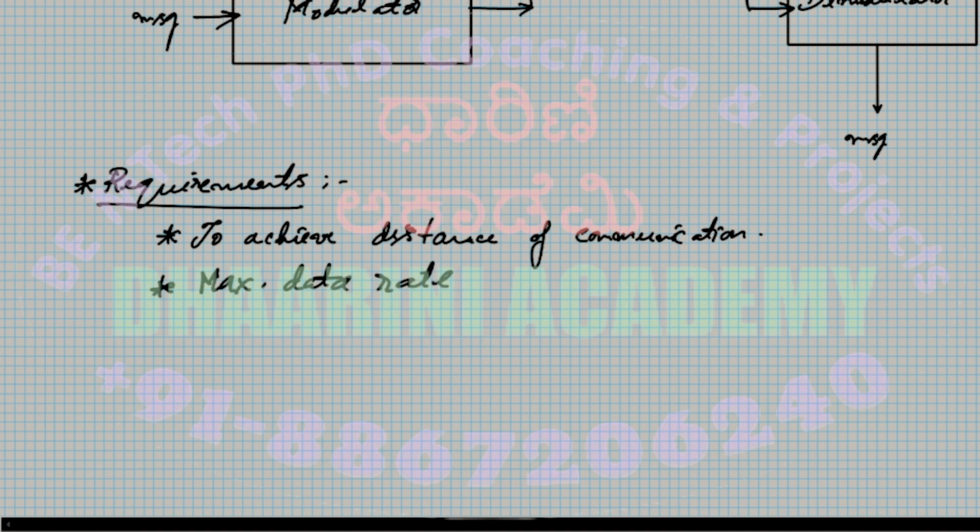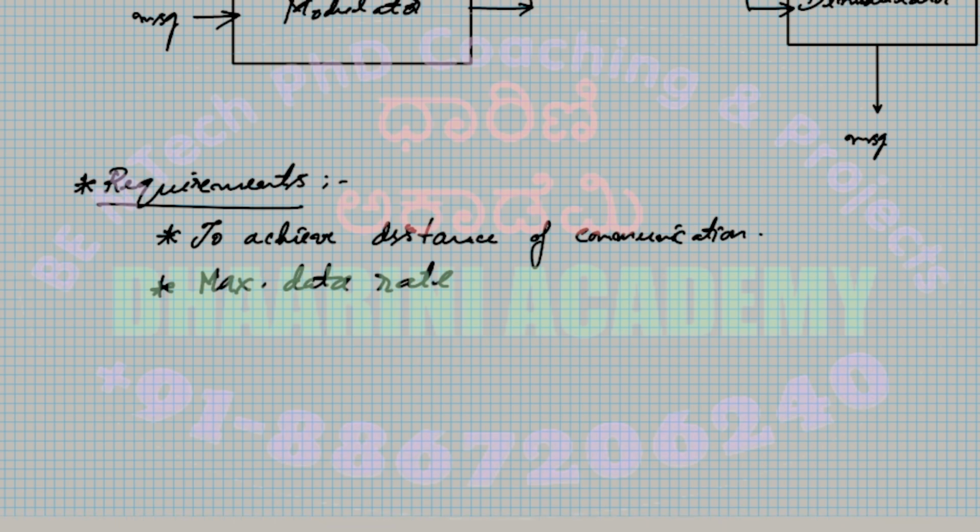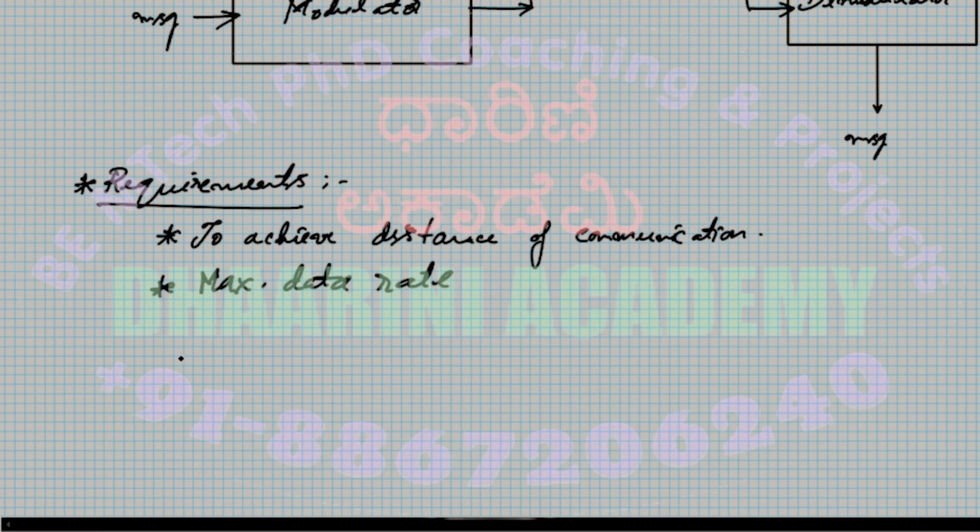That's another requirement here, right? If you don't convert it to digital and you keep it in the analog format and send, you may not be able to achieve the highest data rate. It will remain constant, and it will remain the same as the carrier's frequency. That's the maximum you can achieve. If you come to the sampling part, it's actually half of that, because you always sample at a double rate to satisfy the Nyquist rate. If I have 2 hertz of carrier, that will have only 1 hertz component of the message, correct, because of the sampling requirement.